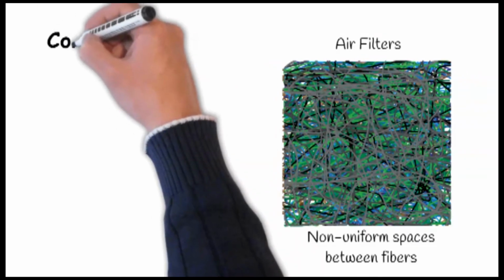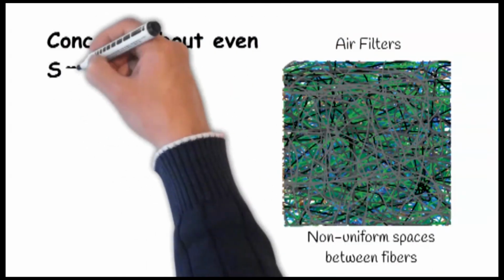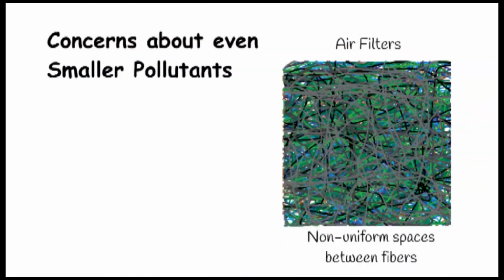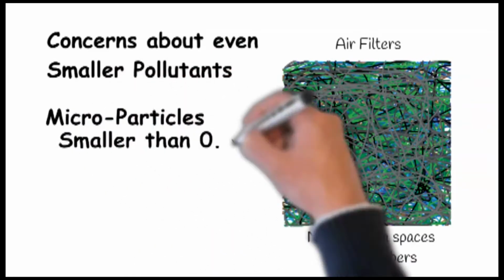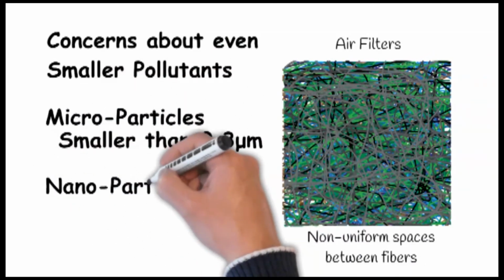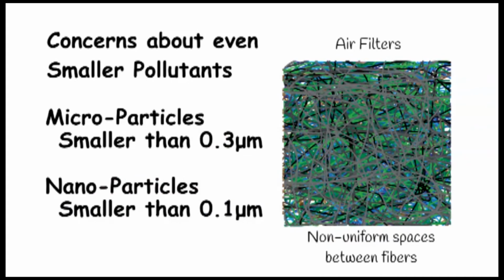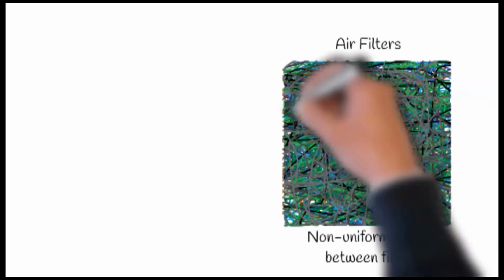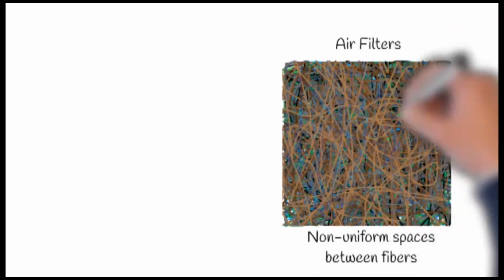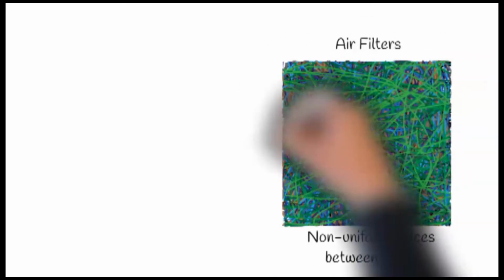Since around the turn of the century, there have been increasing concerns about even smaller pollutants. Microparticles smaller than 0.3 microns, and nanoparticles smaller than 0.1 microns. To capture nanoparticles, filters even finer than HEPA filters are needed.